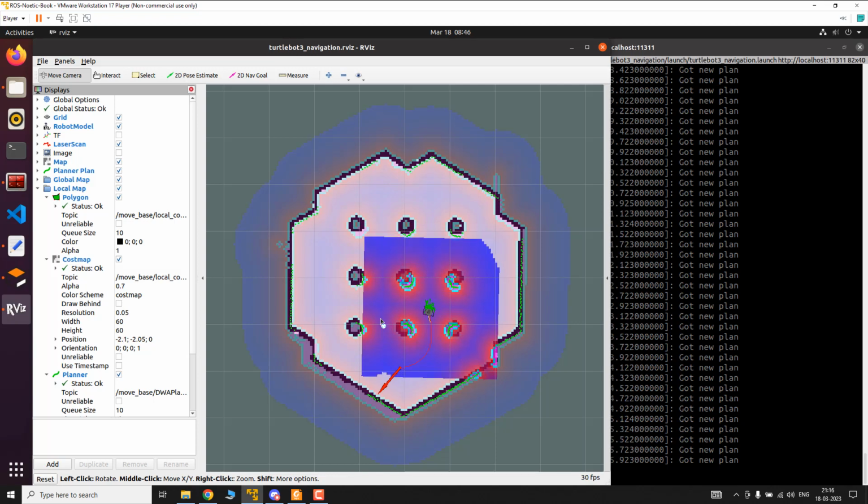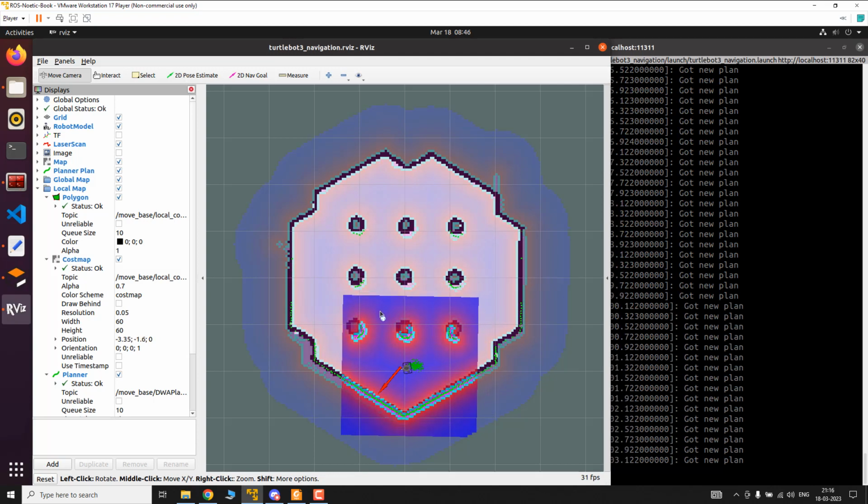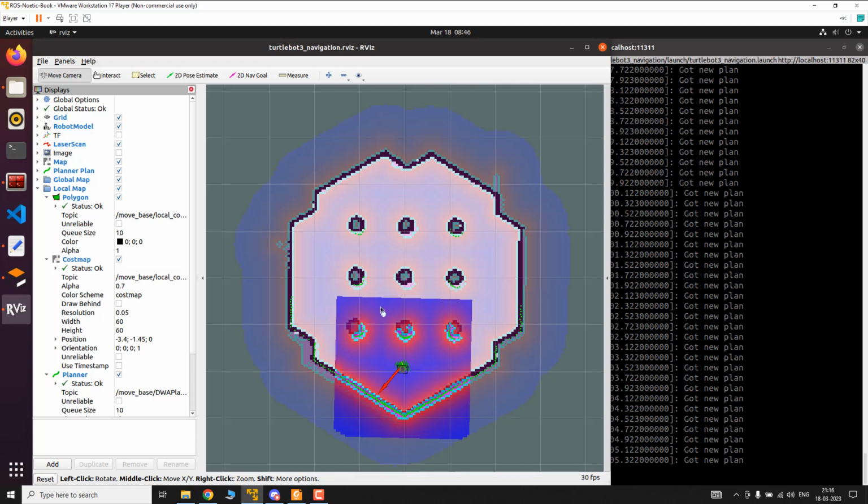So in the case of a ROS service, is this cancelling possible? No, right? When you give a request to the robot, it should complete the task, and only then can we give a new goal. But here the ROS navigation stack is using actionlib. The concept of actionlib is very simple, but the implementation is somewhat difficult. With actionlib, we can give a goal to the action server.